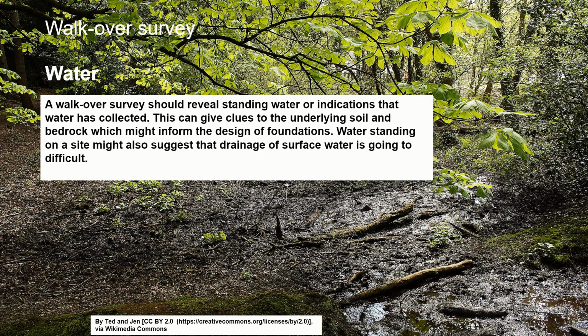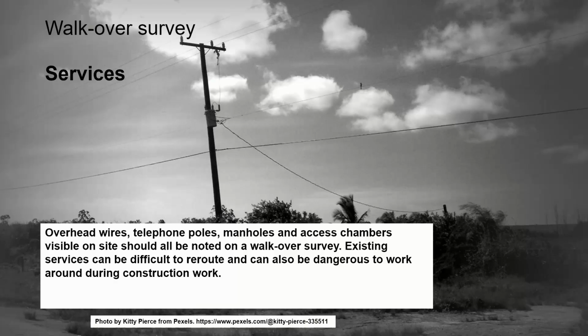And if you do see water, it's worth noting it down and maybe suggesting to the engineer that trial pits need to be dug to establish what the soil is like. So it's a good indicator that there's maybe problems on the ground.